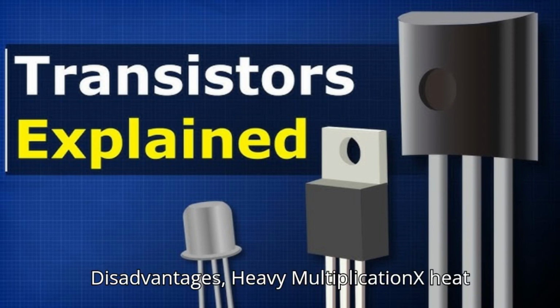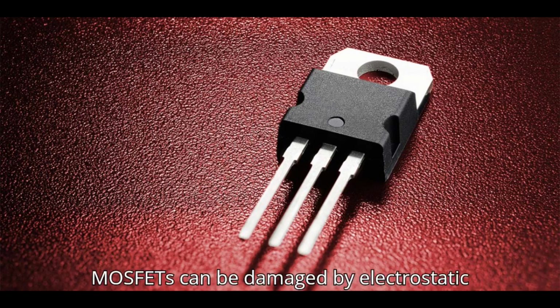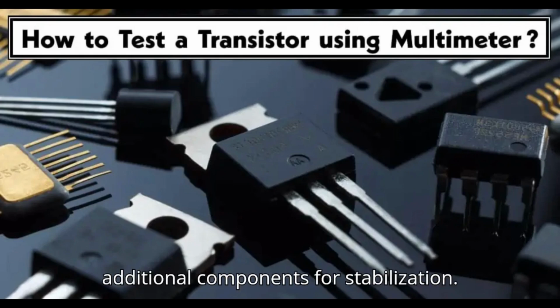Disadvantages. Heat generation: requires cooling in high-power applications. Static sensitivity: MOSFETs can be damaged by electrostatic discharge. Complexity in circuits: requires additional components for stabilization.